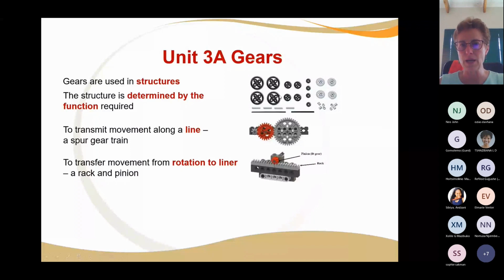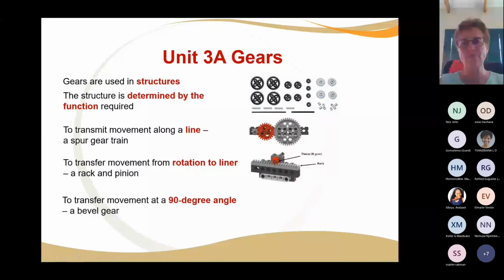Whenever you have three gears meshed, if the power source is on the first gear, it will transfer the rotations via the middle one, which is called your idler, and then to the driven gear. The driver is the gear attached to the motor, which drives the idler, which drives the driven gear. Again, there's a transfer of rotational movement.